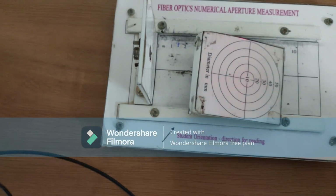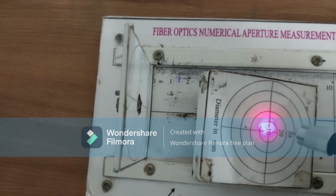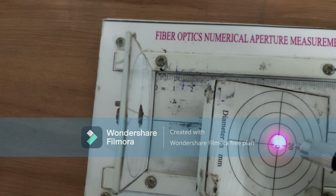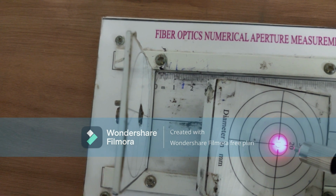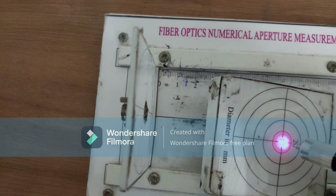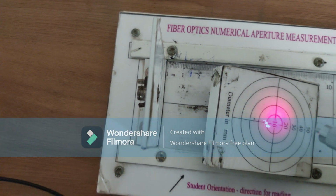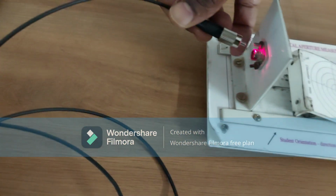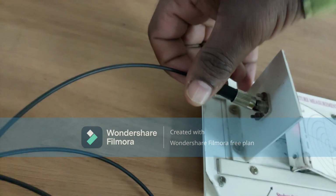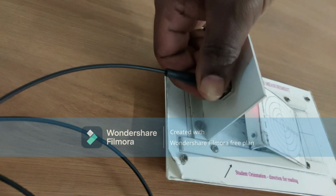predefined ring diameters, now focus the light. Maximum intensity light must be confined to a particular ring diameter of 10. We need to adjust the screen when this optical fiber cable is connected to the numerical aperture jig. So connect this other end to this numerical aperture jig.